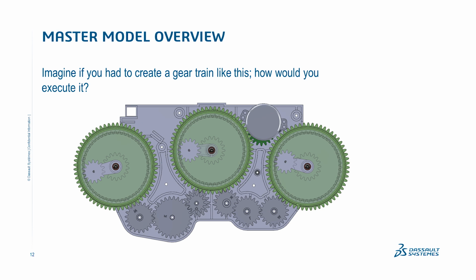I mean, imagine if you had a gear train like this one, for example, where you would, in a master part, create a layout sketch of all the gears and their pitch diameters, and then have that single sketch or a few sketches drive your whole gear train.